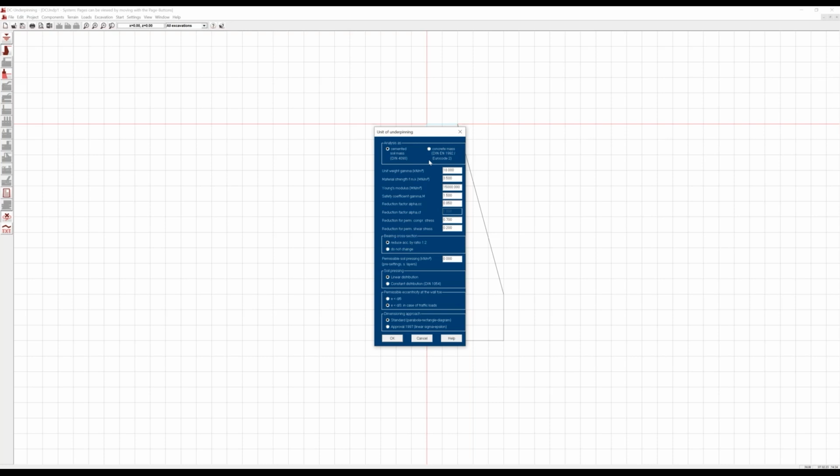This is quite similar, but depending on the material strength, FMK, we have different reduction factors and different safety factors if we change the type of standard. So this is a little different use of the factor to be used for the design of the non-reinforced concrete.